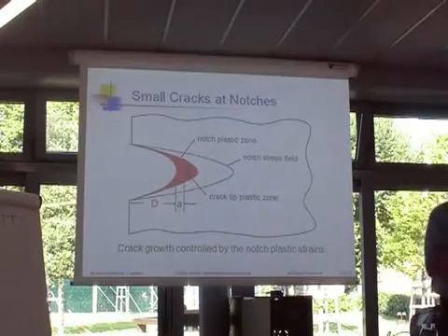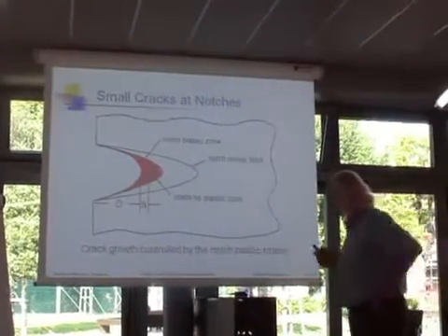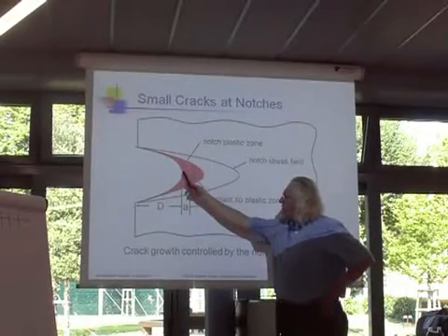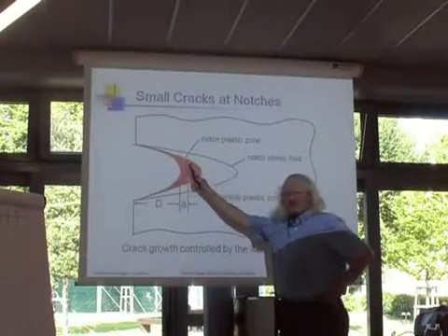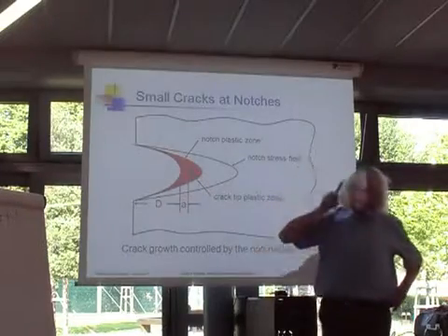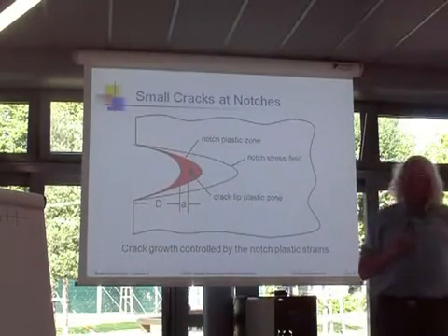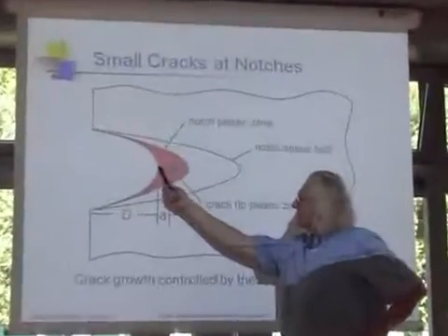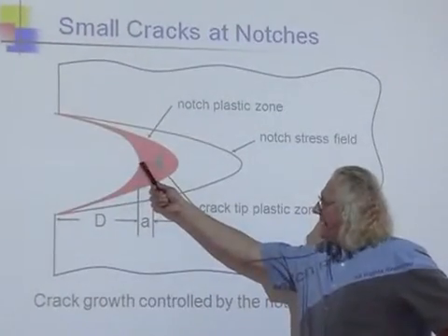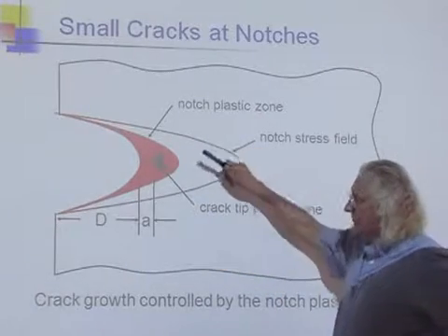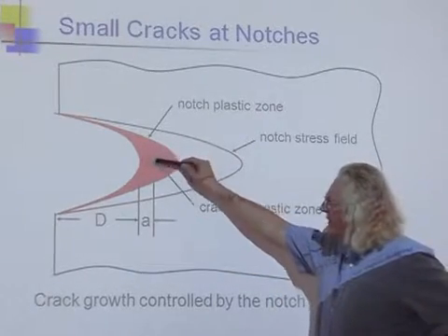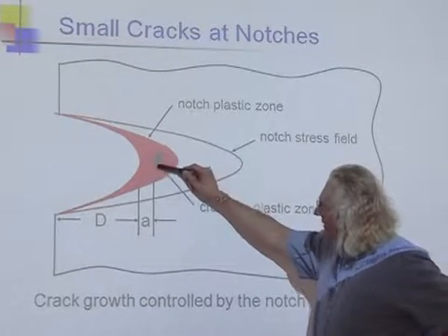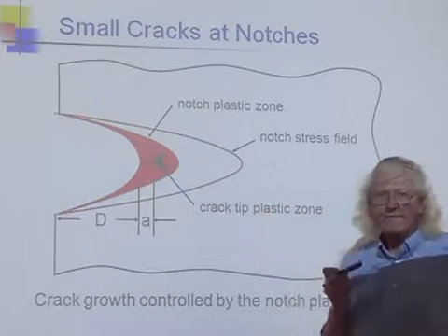And then if you have a fatigue problem, around the stress concentrators you can also have some plasticity which is being driven by the stress concentrator. That will happen in all structures. And then a tiny little crack will nucleate. And when this tiny little crack nucleates, of course there will be a plastic field associated with the crack itself, and I draw that as this little black area.